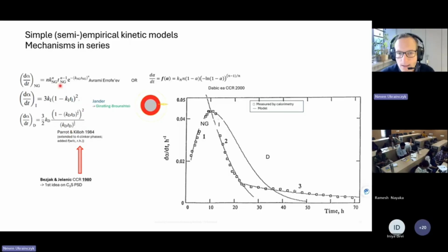And yeah, besides the nucleation and growth, you have also the interaction. You already saw it with me, with the power of 2, because you have the, you know, cement and water, but I modeled this separately, which is better because then you don't have to add the water-cement ratio in an empirical way. And here is the diffusion reaction, which is basically the Jander diffusion.